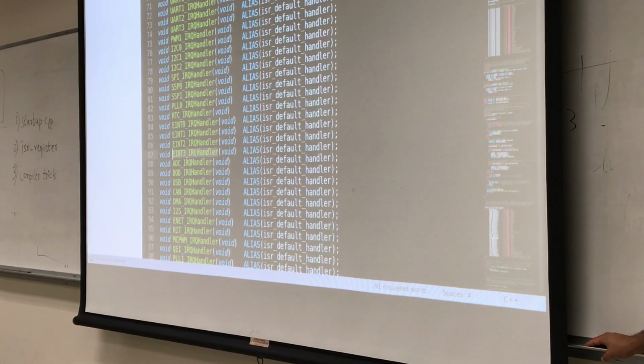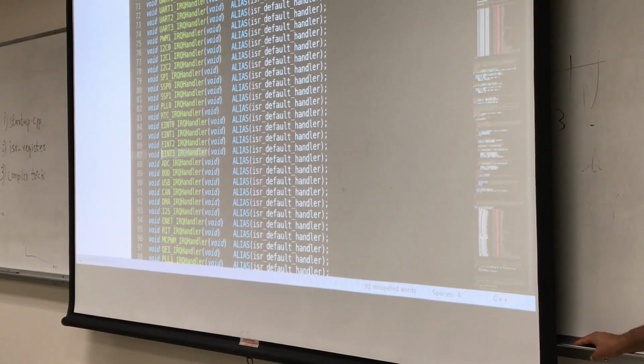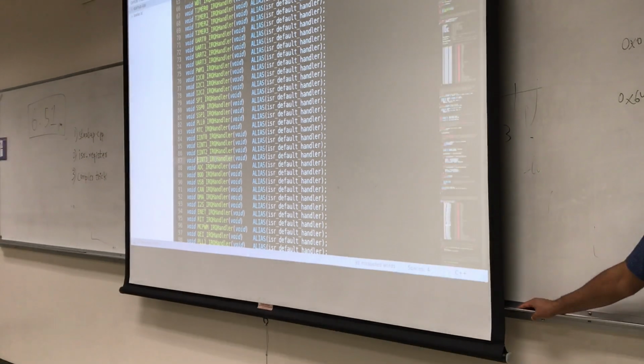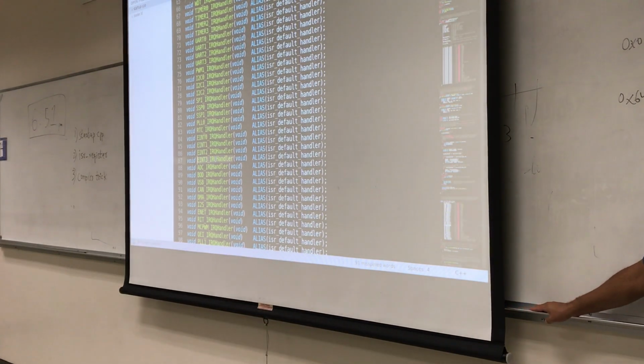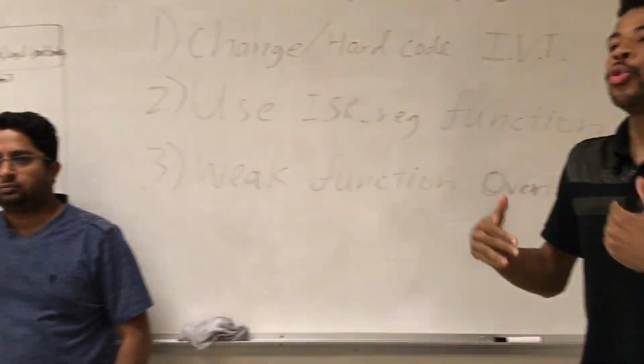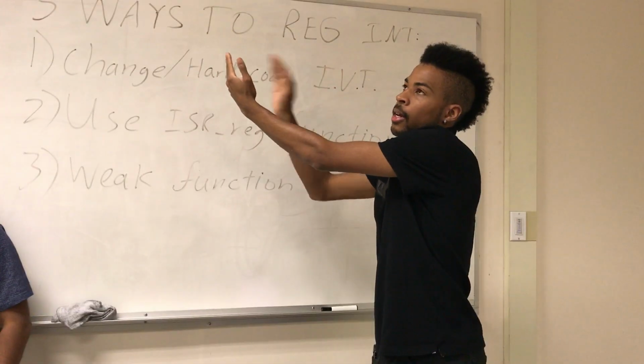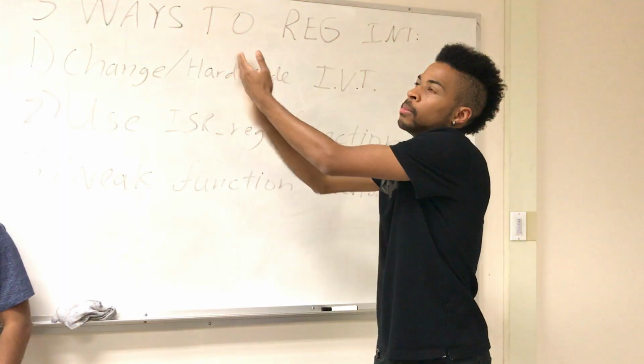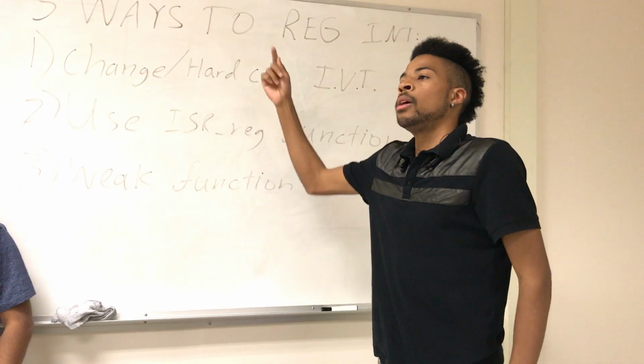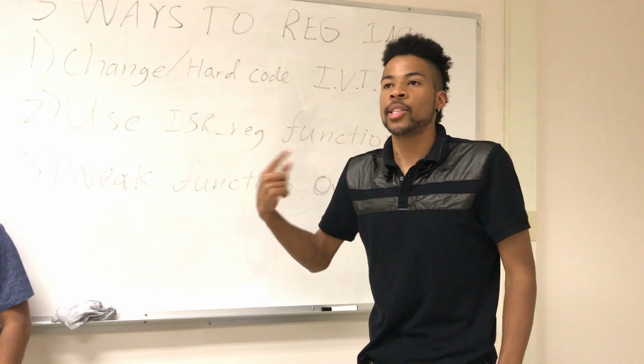When this service routine happens, you have to check a register to see which pin is the one that triggered. So you have one ISR, and then you have a register to tell you which pin actually got triggered. And I believe you can also find out what state, like how it got triggered. Not super important though, just that it did get triggered. So you can check which particular pin got triggered by looking at the interrupt status register. Run that service routine based off of which number you got.